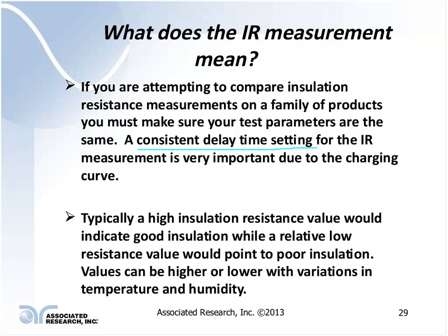Temperature has a great deal to do with your insulation resistance measurement also. If you're testing motors and stuff like that, there is a temperature conversion factor that must be taken into account. There's actually an IEEE standard for insulation resistance testing. Offhand, I don't remember what it is.